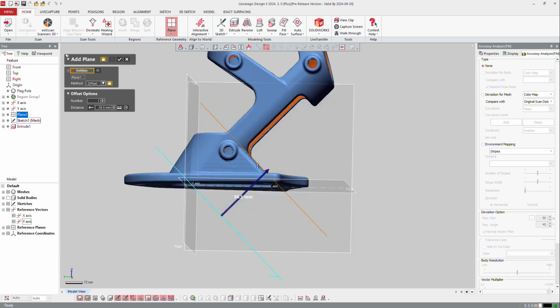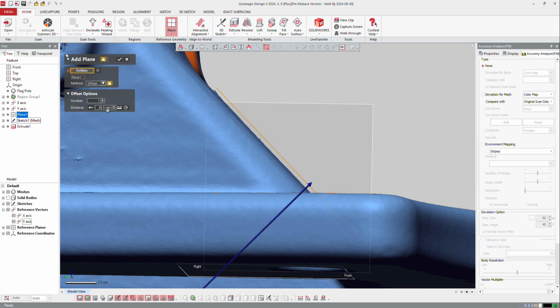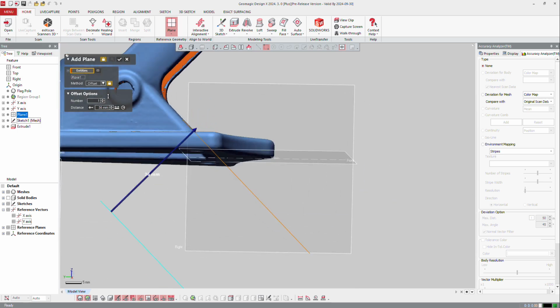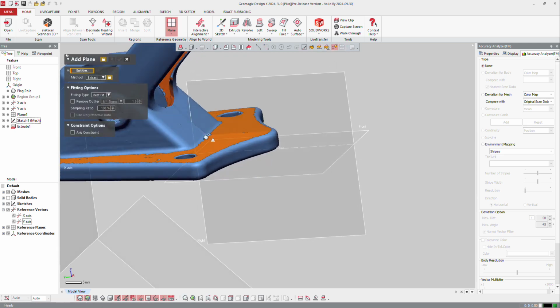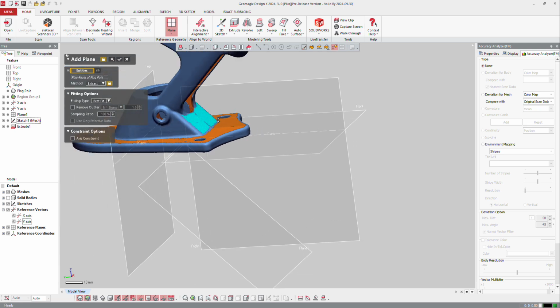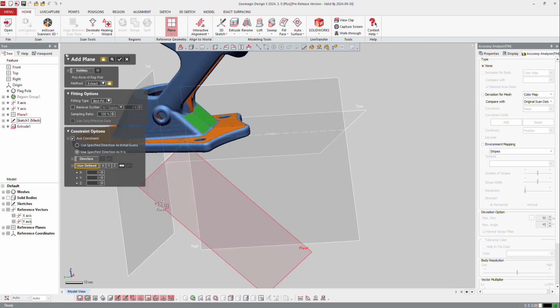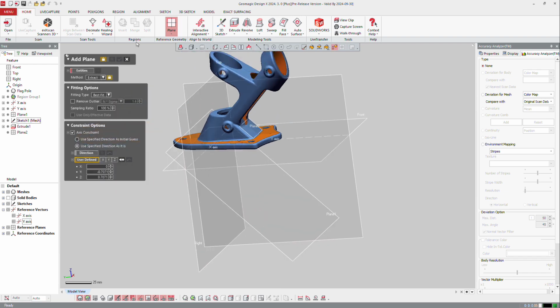So I can either do that or make a mesh fit, maybe 35 or 36. Okay, if you don't want to do that, I can make a fit, so instead of offset, extract, get the automatic extraction here, and ask the software to constrain my axis based on that plane. That's going to be easier to do that.